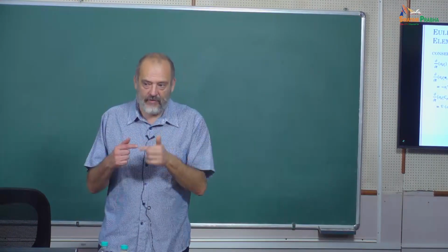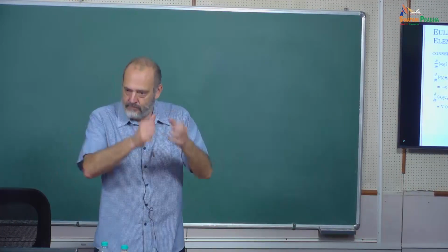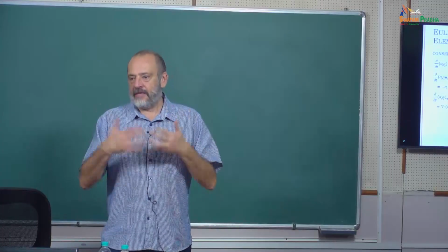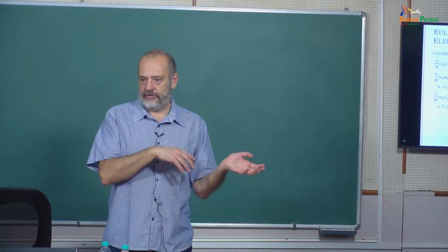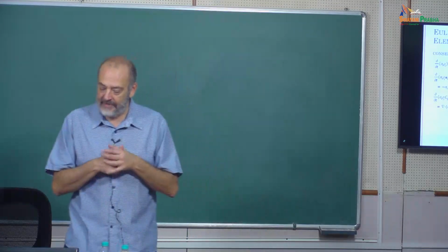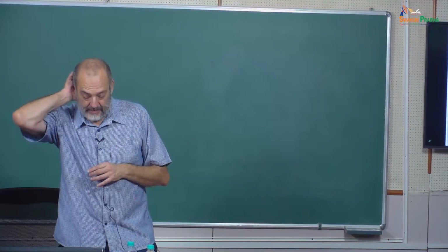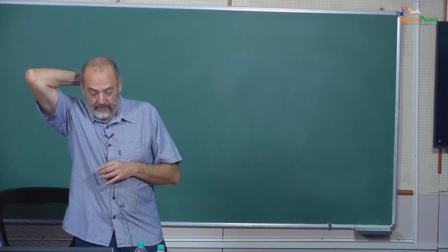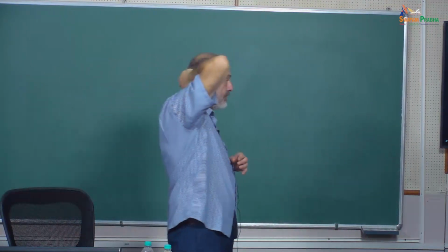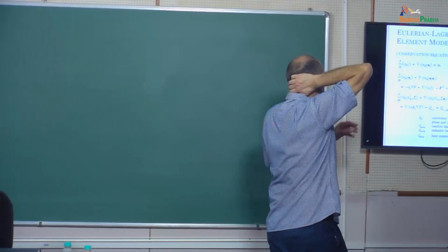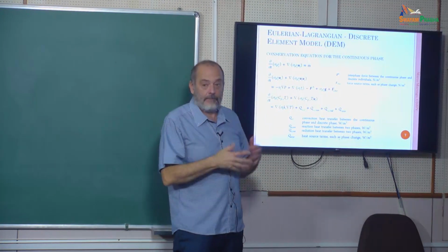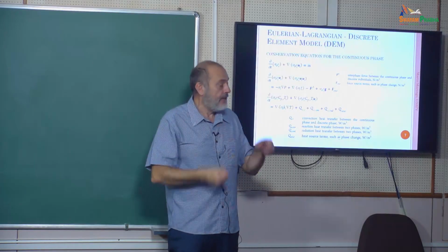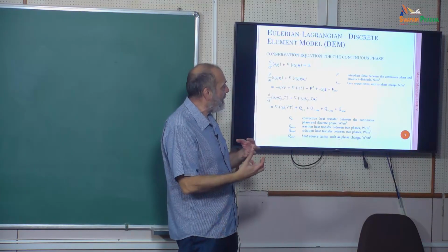So if we have a phase change, we need to put one term that is linked to the fact that we have a liquid that is going to vapor or vice versa. Then we have another important term, the momentum equation, which also contains the interface force between the continuous phase and the discrete parcels, so the force between them.